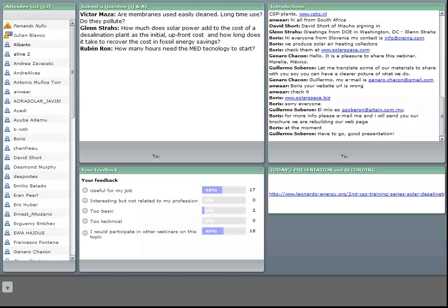This is especially a challenge when we think of integrating it into solar power plants, because a solar plant is typically designed to be stopped at night. Even if you have thermal storage, it could work a number of hours, but you stop and you start again the next morning. But the MED plant should continue during all the night.